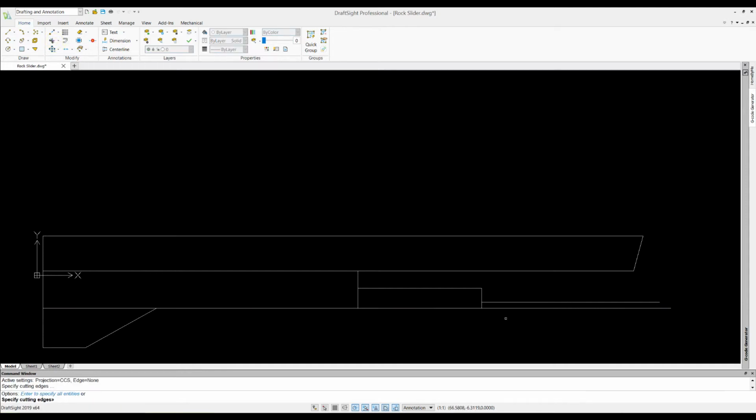So let's go ahead and trim off what we don't need, just to not have it in our way. So we don't need that. It won't let you trim something that's short already. Since that's its own line, it won't let you actually trim that. So we'll actually have to delete that first. So we'll wait. We'll trim this though. Oh, what are you doing? Trim. Oh, we drew a line there. So I'm going to escape. Let's delete that. There we go. And then let's delete this. So now there's a line that needs to be trimmed, and we'll trim that one right. Oh, we need to trim this too.